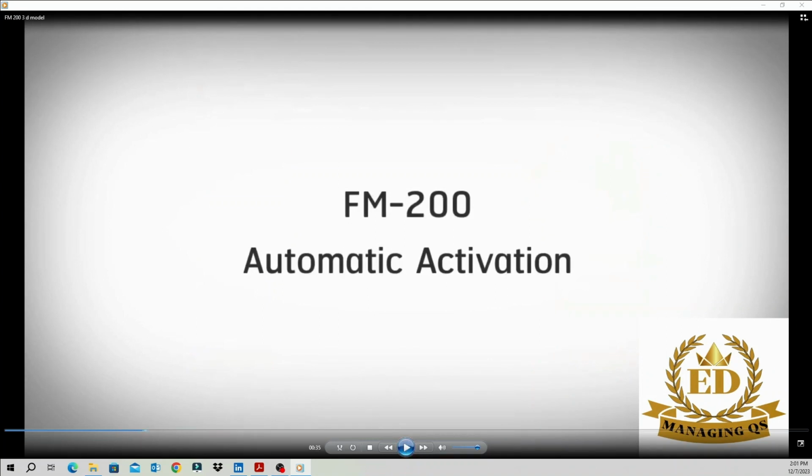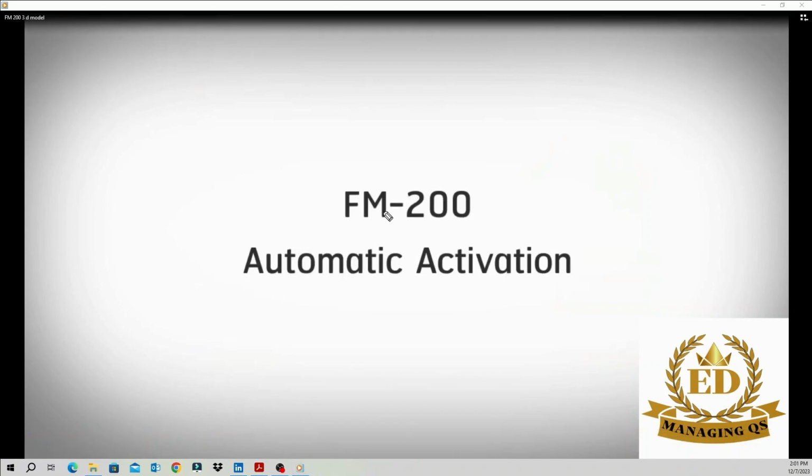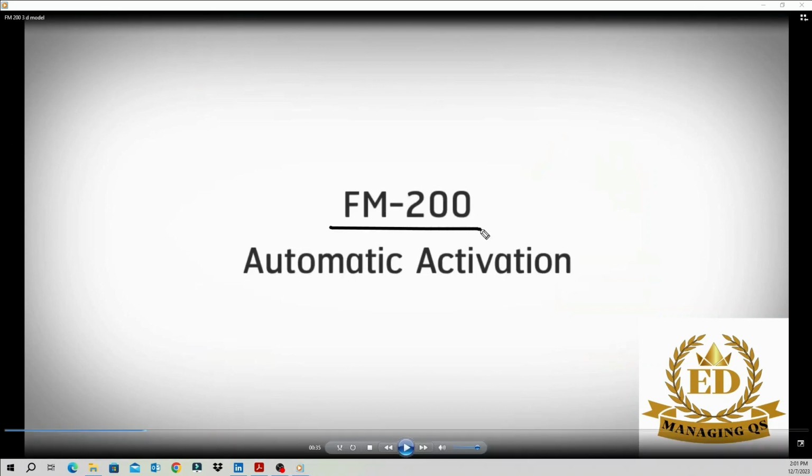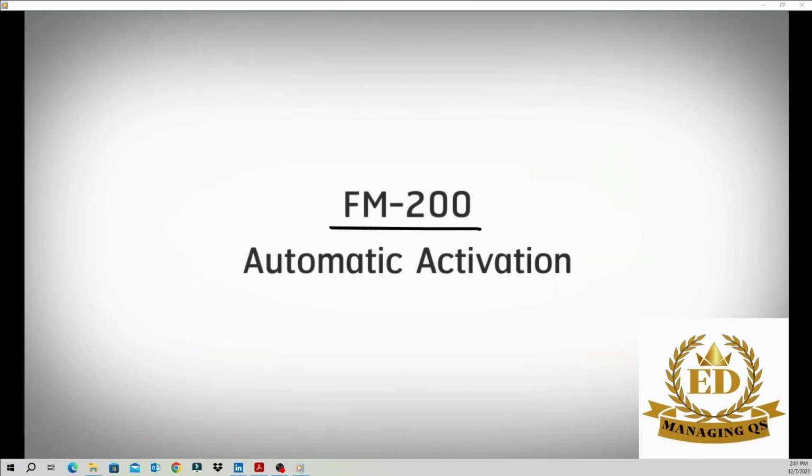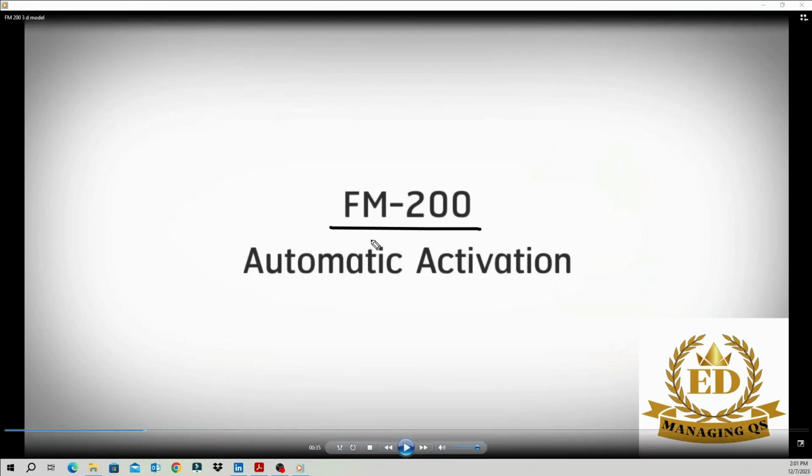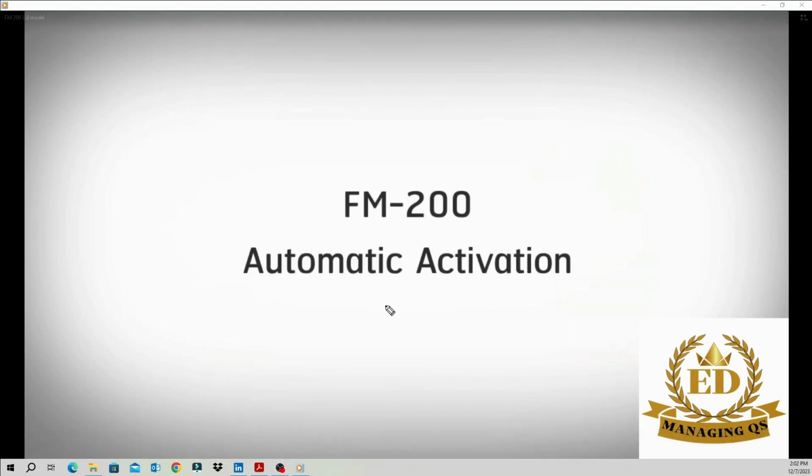The first main technical point is that the FM200 system can be activated in two ways. The first way is automatic activation. The second one is manual activation. We will discuss that later. So now we are going to discuss automatic activation. Okay, right. We will move forward.